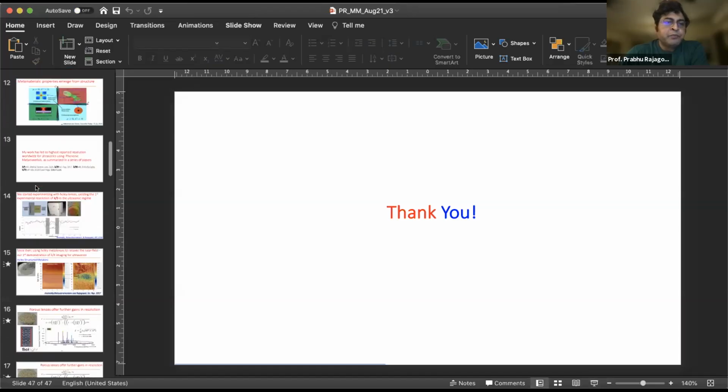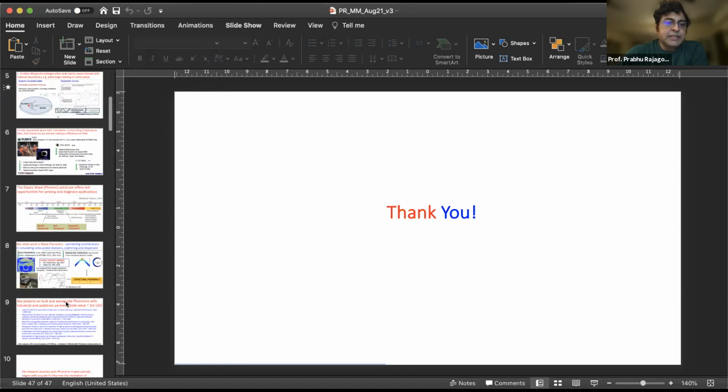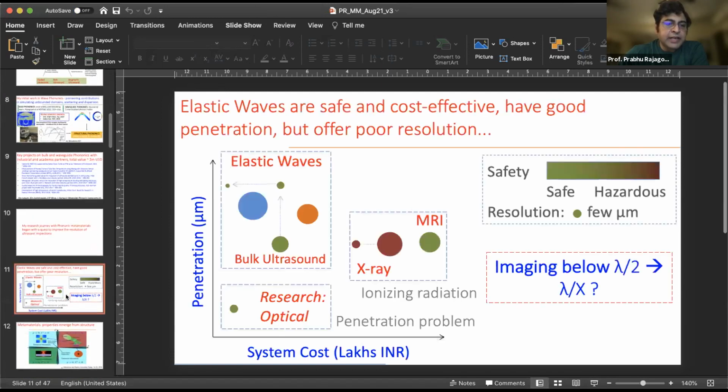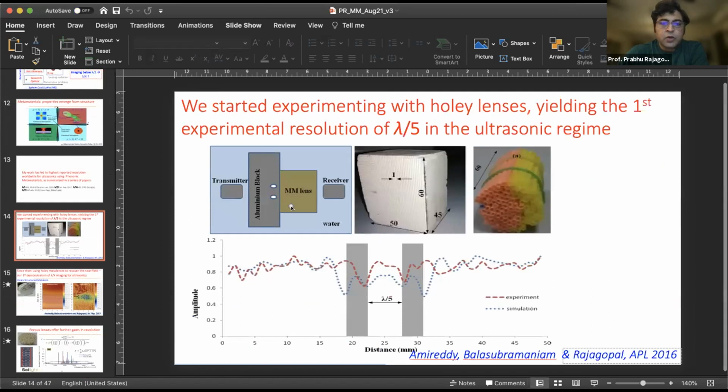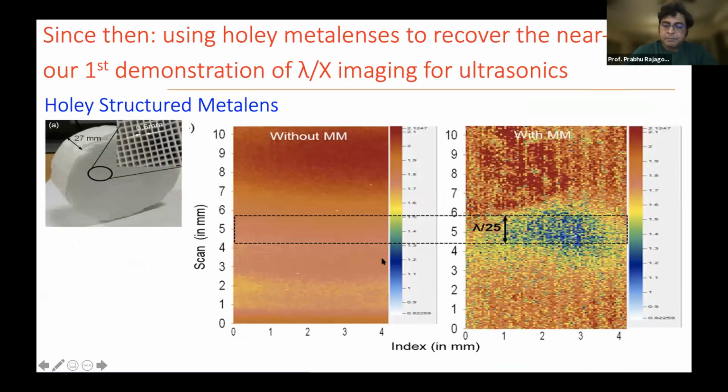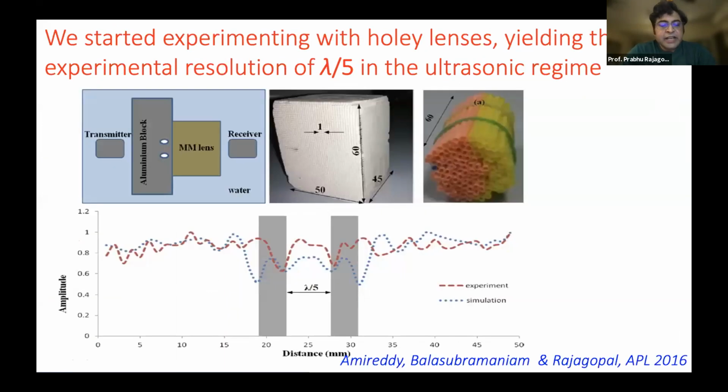Yeah, so essentially what happens is when a wave is scattered past a feature such as a defect, as in this slide, for example, the scattering happens at very high frequencies. The feature will transmit wavelengths that are much, much smaller compared to the incident wavelength. And at these wavelengths, the wave is highly attenuated, because that's why these are called evanescent waves, or waves that exist at very small distances from the source.